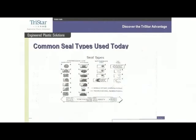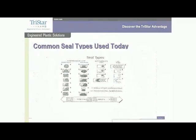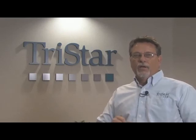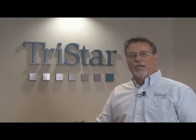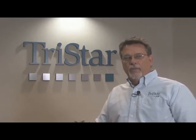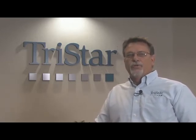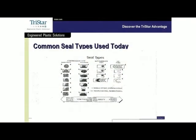So if you look at the true lip seal designs, which also include other types of chevron packings like PTFE chevron rings, an asymmetrical or symmetrical urethane seal that is machined or molded in a condition to where the basic design allows you to operate without an O-ring or an expanding ring. Those are true pressure-sensitive lip seals. And at the bottom you see there a PTFE spring energized seal, which we will be talking about.